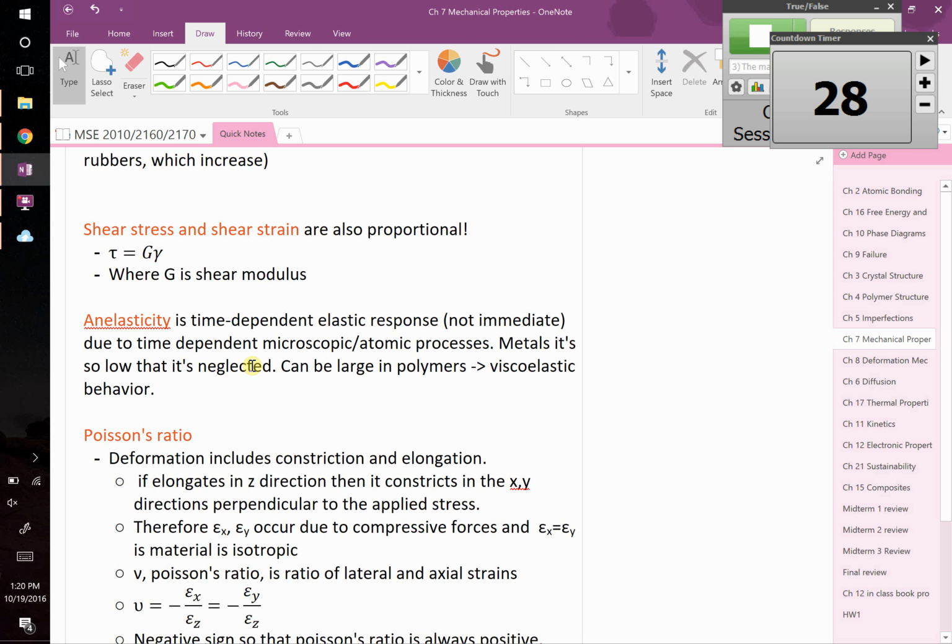Eric, question? Just kind of a concept question. If you have a material that gets stiffer when you heat it up, does that mean it will burn rather than melt? That's a very good indicator of it. I don't know if that's 100% of the time, but it probably means that as you're heating it up, your cross-linking process is continuing. It's using that thermal energy to further cross-link, or maybe thermally cross-link. And therefore, if it's cross-linked, it's not going to melt. As cross-linking goes up, it's getting stiffer. There's probably exceptions to that rule, though.